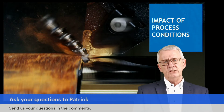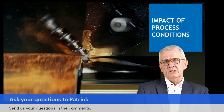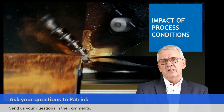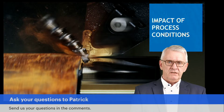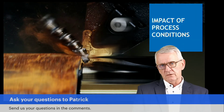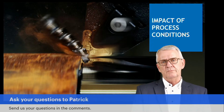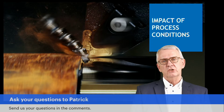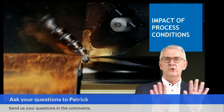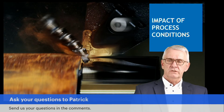Machining, the deformation of material, generates heat. And that heat shows a tendency to spread out. And the level to which the heat can be spread out depends heavily on the workpiece material, see thermal conductivity, see specific heat. And as heat can spread to the chip or to the workpiece material, less heat goes into the cutting edge. But if that is not possible, take for instance if you machine titanium materials where the chip kind of says, no heat for me, I don't take it, the heat which is generated then goes into the cutting edge.